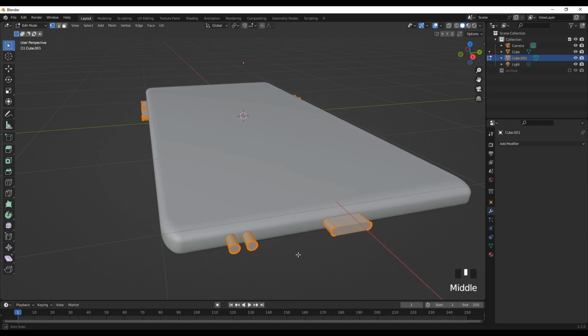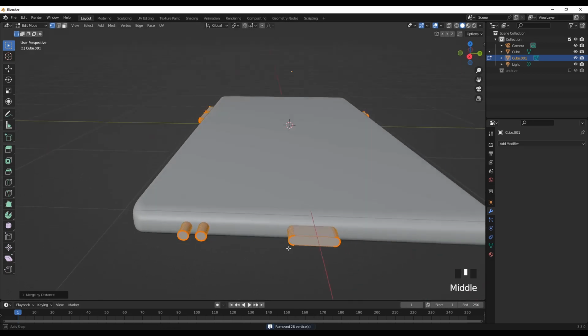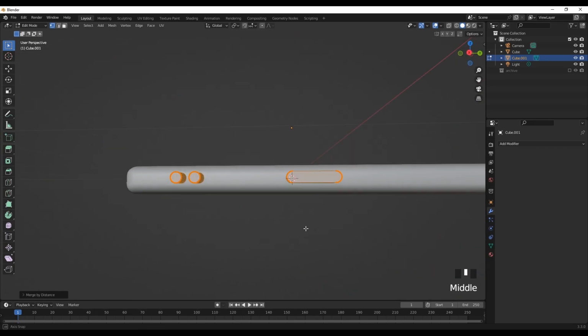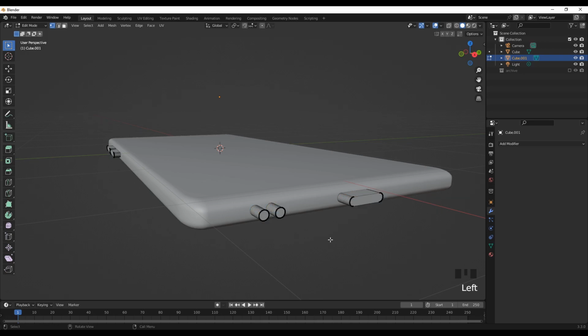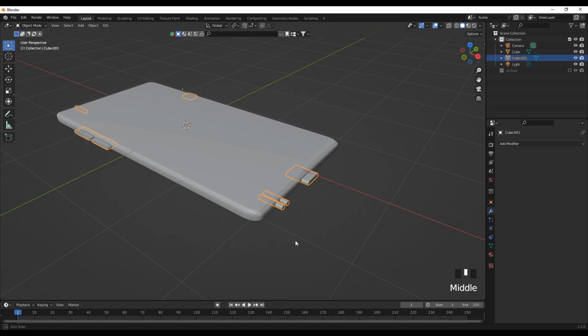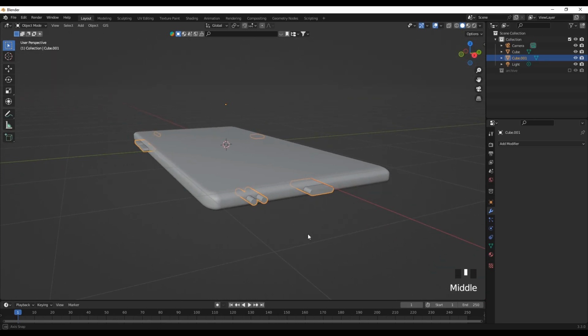Okay, for these parts also we need to check their geometry. Press M for merging by distance, and 28 vertices have been removed. Now their respective geometry is workable, it's clean. Alright, now the stage is ready for the Boolean operation.